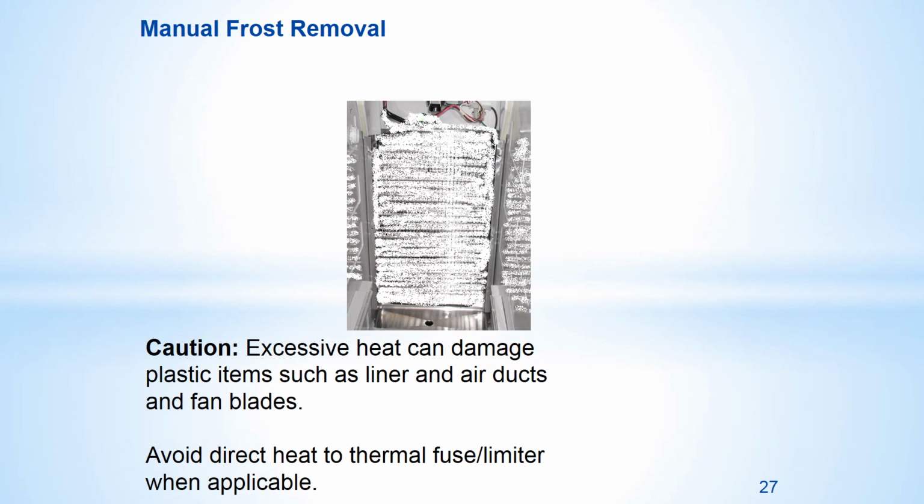Manual frost removal is necessary even after you have repaired the defrost system. Frost remaining on the evaporator or in air ducts will generate a recall. Caution: excessive heat can damage plastic items such as liner and air ducts and fan blades. Avoid direct heat to thermal fuses or limiters when applicable. Heat can warp and melt plastic easily.